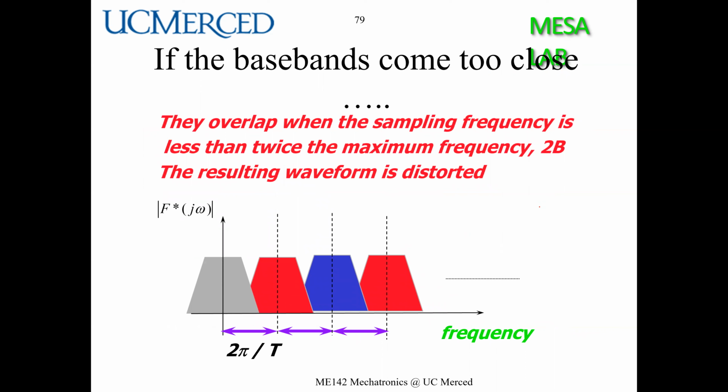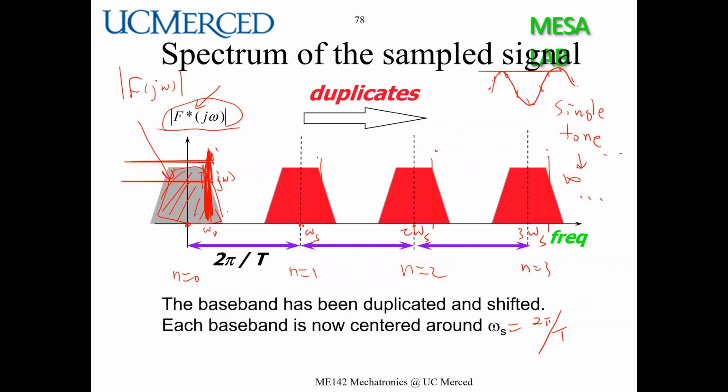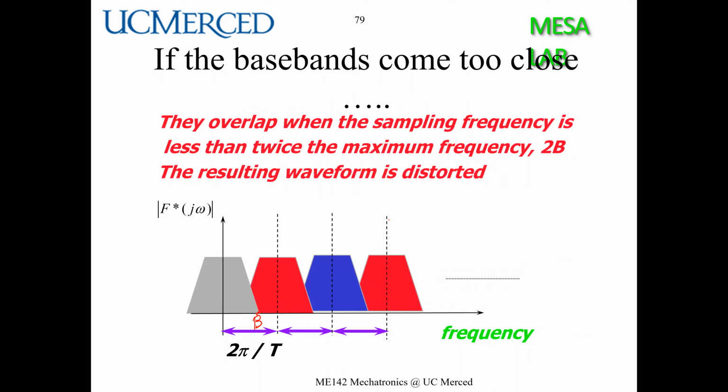But unfortunately, remember, we got something called B in here, right? So we are going to have a band limited signal, and everything beyond the frequency B will be 0, okay? Everything beyond the B here is 0 in the continuous time domain, okay? However, after you sample it, if it is sampled not fast enough, therefore there is an overlapping here, okay? So then this region is called ambiguity, okay?